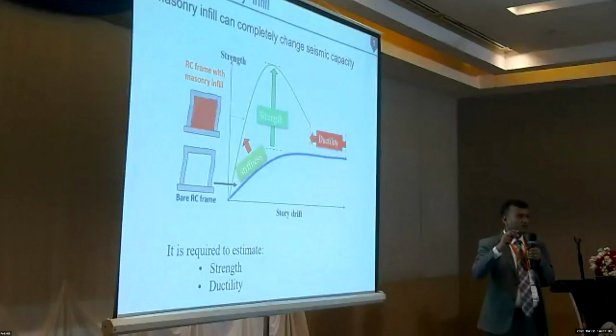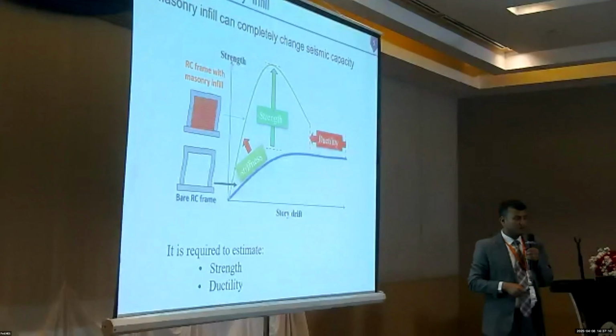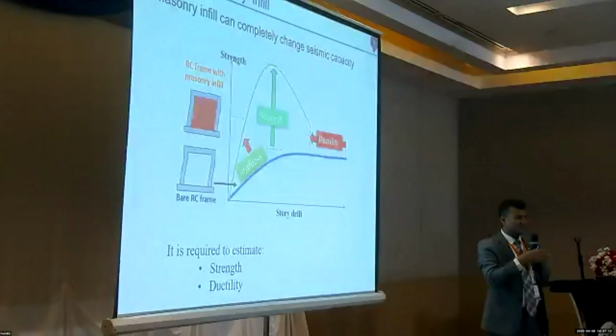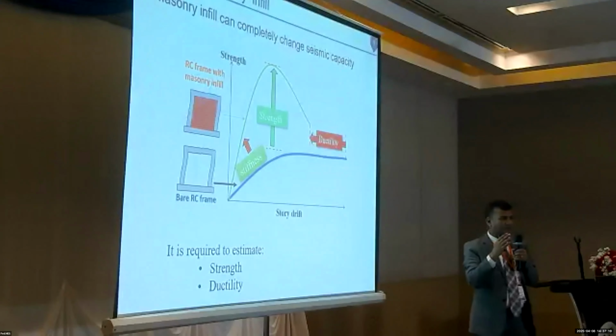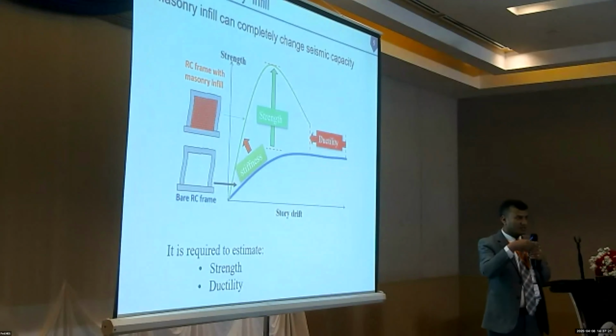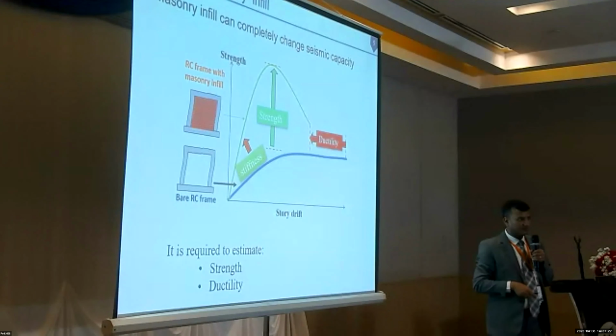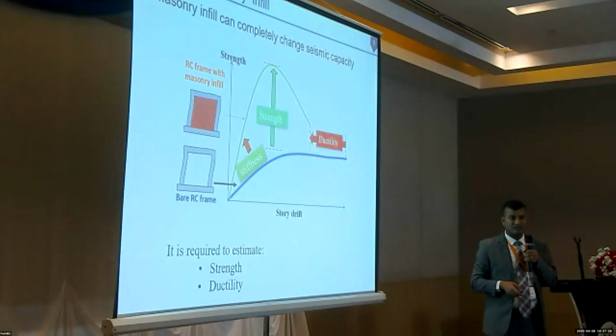Infill is connected with just the normal mortar, only mortar? Just mortar, yes. This is a common practice in Bangladesh, we just put mortar. But in case of out of plane failure, if we put some other technique, maybe it is helpful to prevent the out of plane failure. Thank you.